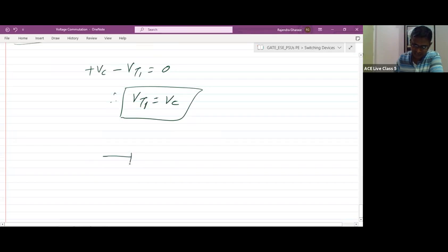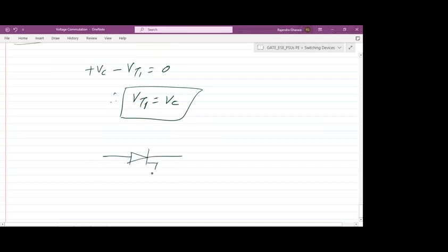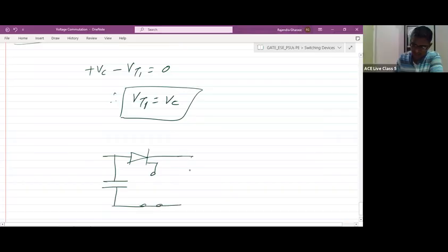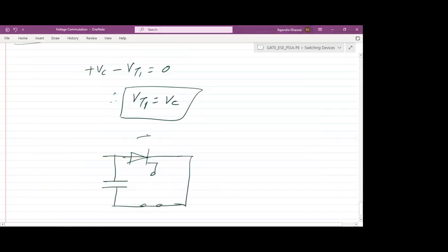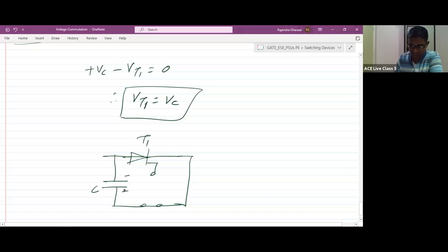This is like our thyristor we are having. Here it is a capacitor. Here it is the auxiliary thyristor we turned on. The main thyristor is also in the on state. This is a capacitor which is charged to minus here, plus here. This is Vs. As soon as your auxiliary thyristor turns on, this capacitor will try to discharge like this.